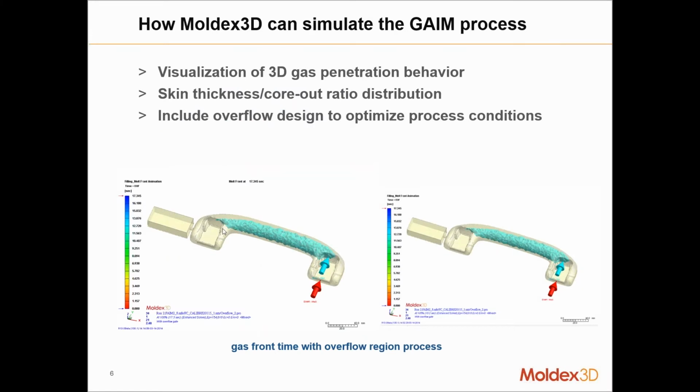One of the main disadvantages of using the gas-assisted injection molding process over something like MuCell or some other foaming process is that the actual behavior of the gas, how that gas distributes in your part, is quite unpredictable. Once you nail down the process and are able to replicate it reliably, the gas penetration is usually pretty consistent.